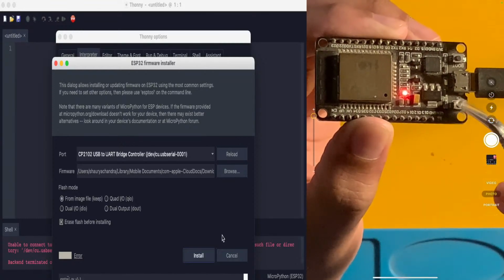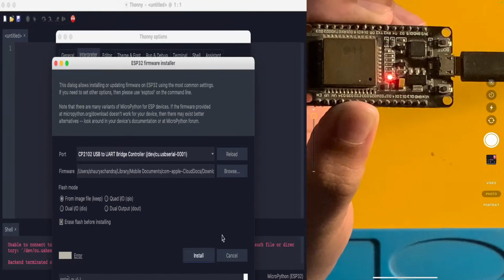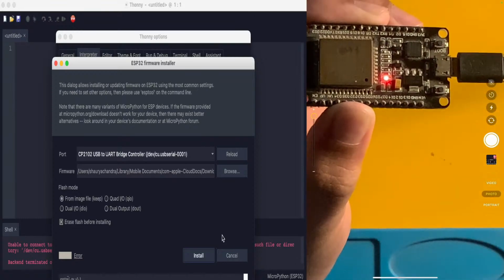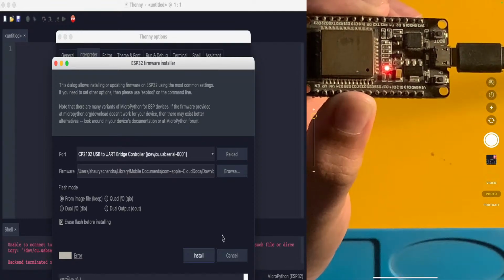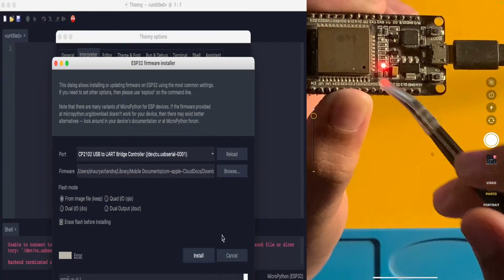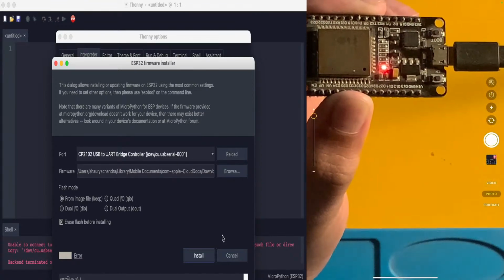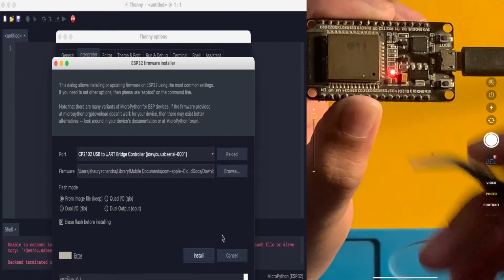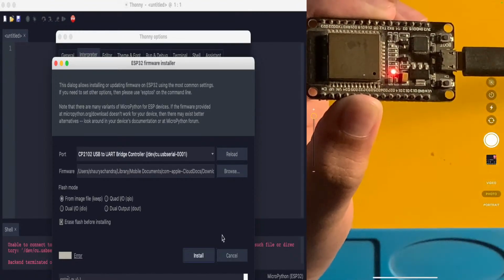When you click it, it goes to 0 and hence you disable the IC, and when you release it, it again goes back to 1, just like the pull-up feature that I told you in the beginning, and the chip gets enabled. So you're disabling and enabling it. This entire process is known as resetting of the ESP32 microcontroller, of any microcontroller.